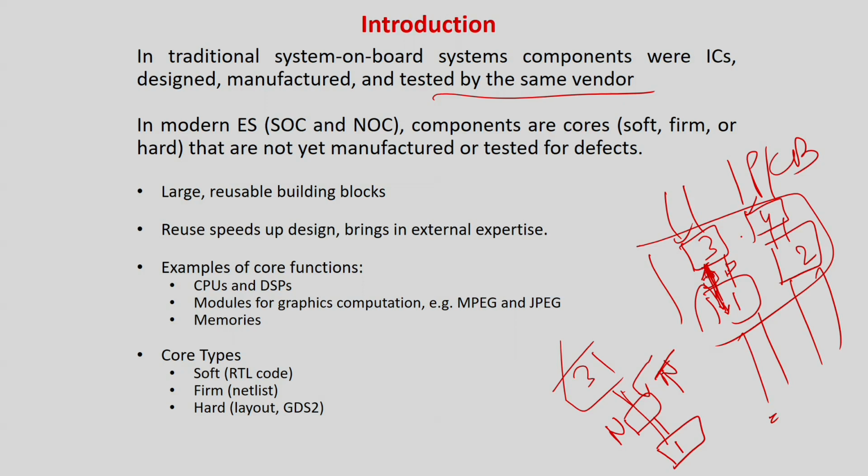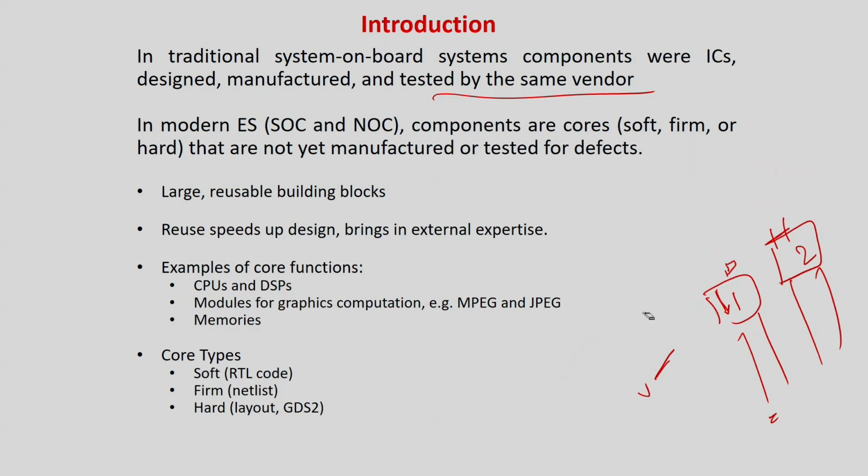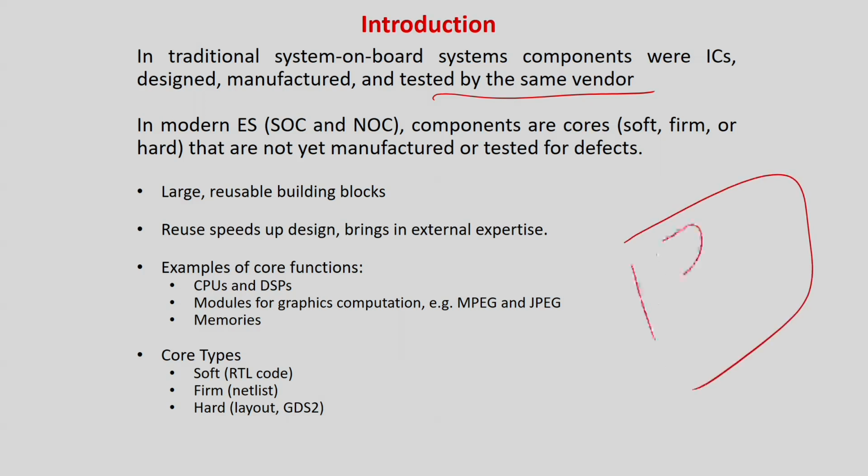So, I can easily put some kind of multiplexers, because in the previous days I used to procure all these chips and put them in a board. So, wherever such difficult to observe and control lines were there, I can make a multiplexing arrangement. But in the die, sometimes it is very difficult to do, because there are a lot of other issues like loading of the pins, etc. This is a big die, and you are putting some of the IP cores here.